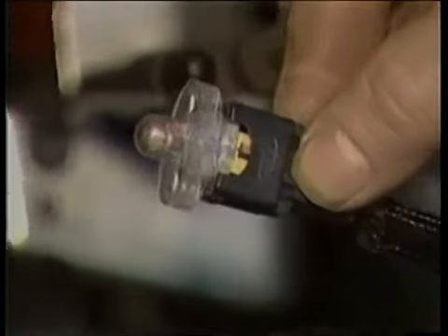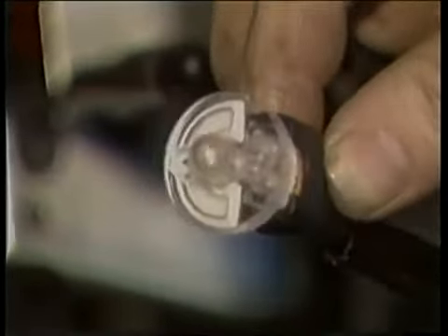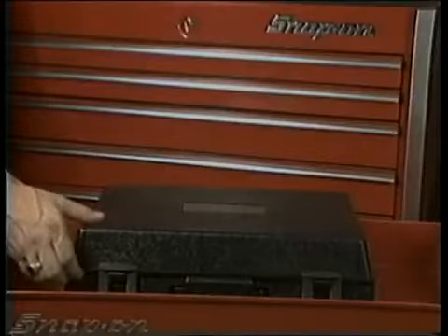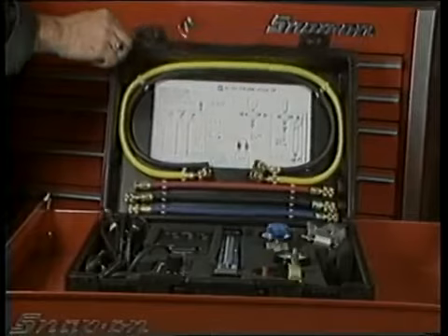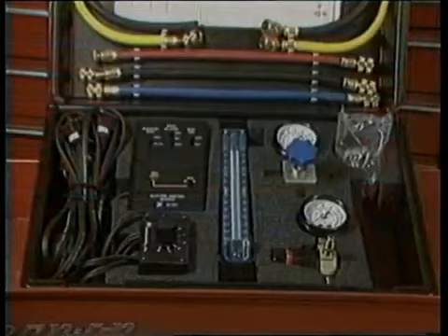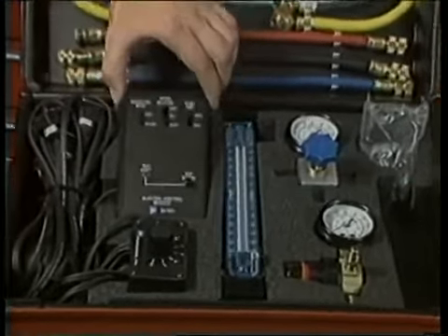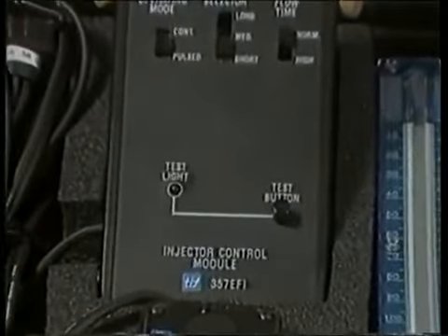If an injector is not firing and clicking, check for computer pulses going to that injector with a high impedance test light. If the test light shows pulses are reaching the inoperative injector, the injector is probably bad. If you suspect clogged or spitting injectors, use an injector tester like this one. It checks the fuel injector by directly observing the volume of fuel injected when triggered by an injector control module.